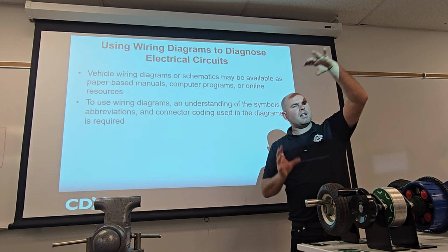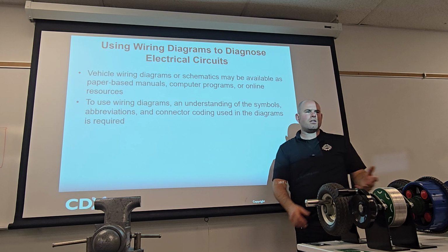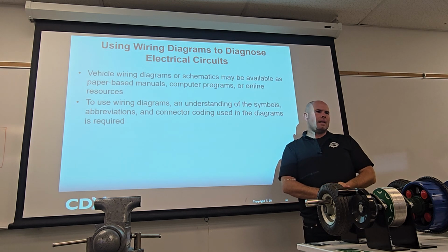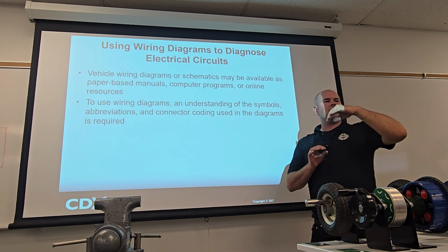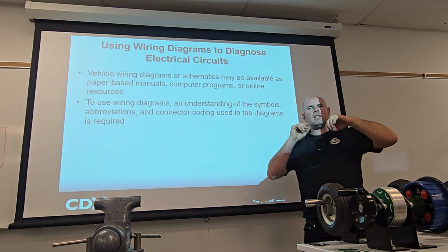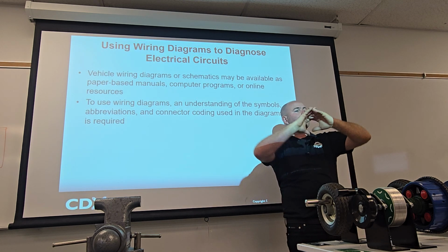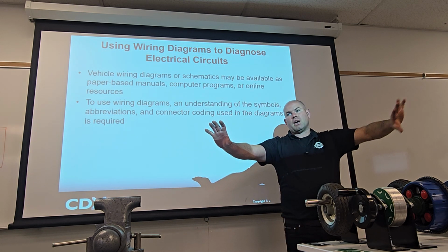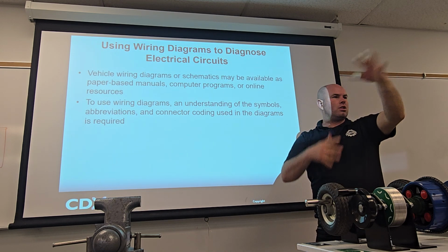If it's a whole big LED assembly, I could put a whole big LED assembly in there. I think those are like $400. So do I want to just do that? Now I better do some diagnosis. If it's something that's flickering, it sounds to me like there's resistance inside the LED circuit board, right? And that's possible. So if I replace the LED circuit board, then it's good, right?